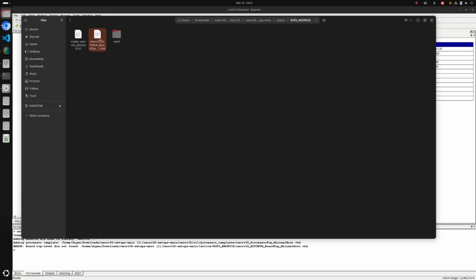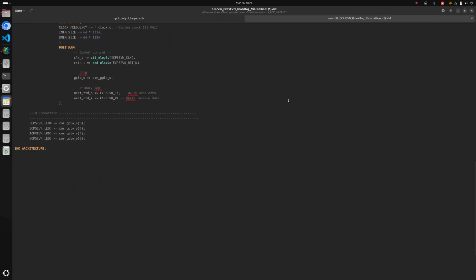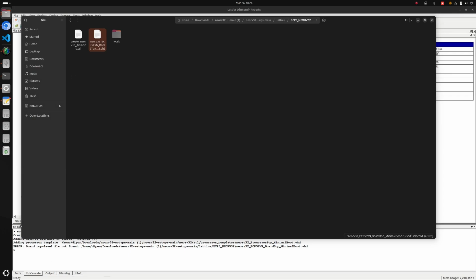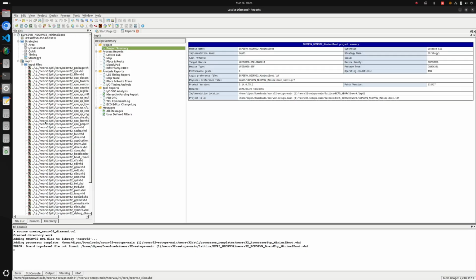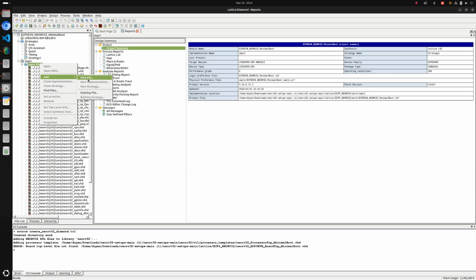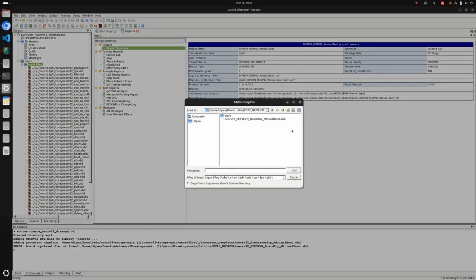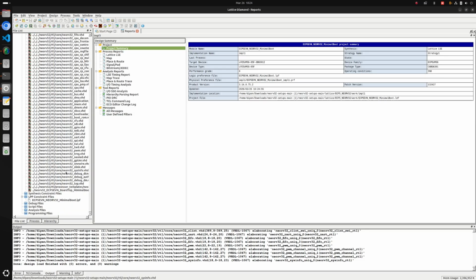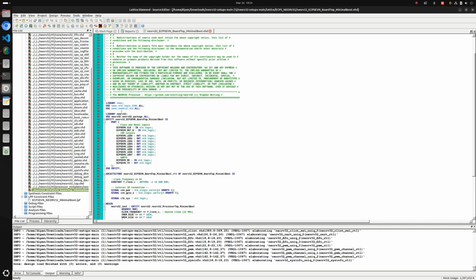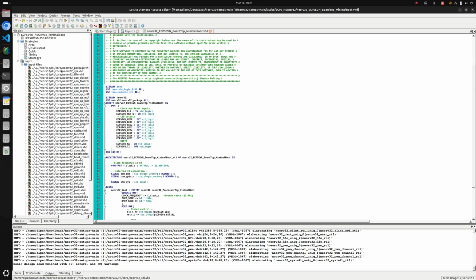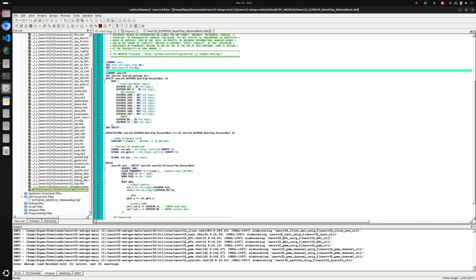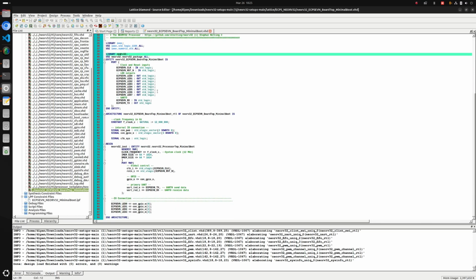I'm not sure why it did not. Look at this. Okay, I see. This one became a problem. So yeah, we'll just add it manually because it happens. These files, add existing file, library. So for this project and how the TCL file handles it, all the NEORV32 files and the actual top level file live in the NEORV32 library.